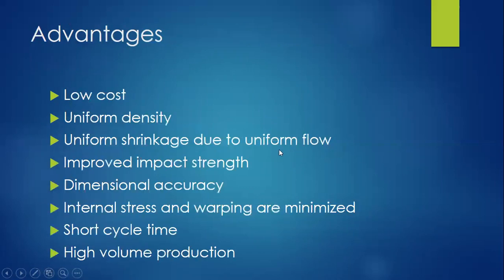What are the advantages? Advantages are low cost, uniform density, uniform shrinkage due to uniform flow, improved impact strength, dimensional accuracy, internal stress and warping are minimized, short cycle time, and lastly, high volume production.